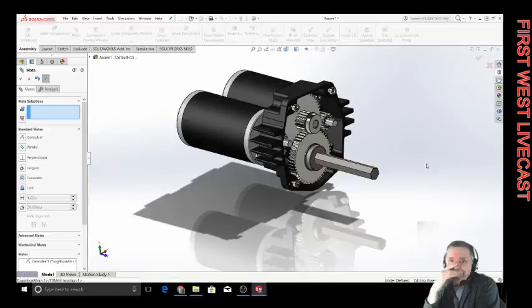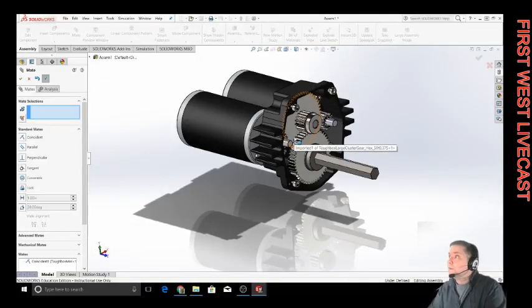As I say, the most difficult thing in SolidWorks to get a properly built model is you've got to make sure that it's properly defined. You can see right here where it says underdefined. This indicates that this thing has some ambiguous dimension somewhere. It doesn't know exactly where it fits in space, either X, Y, or Z. There's some dimension in there that's undocumented. So a good SolidWorks modeler will make sure that this little text right here says fully defined. That's the cat's meow.